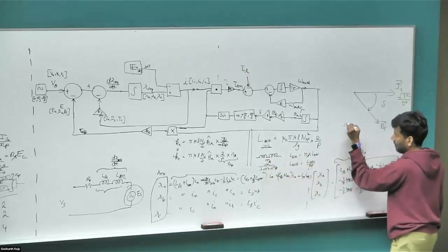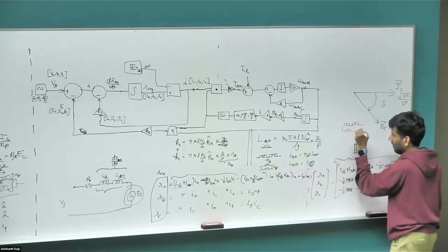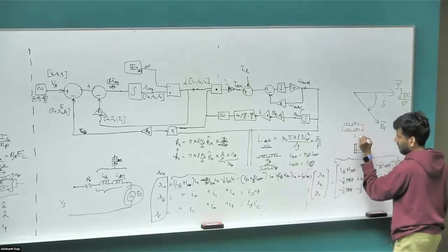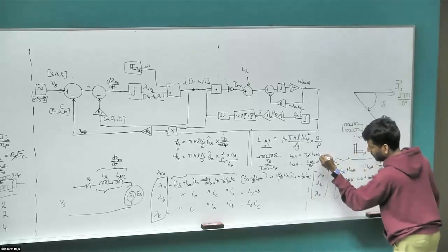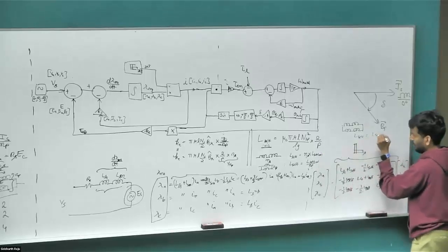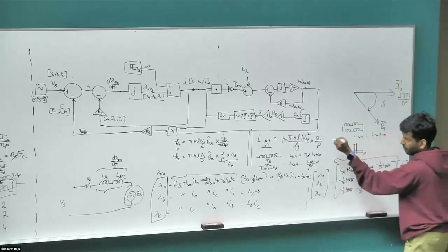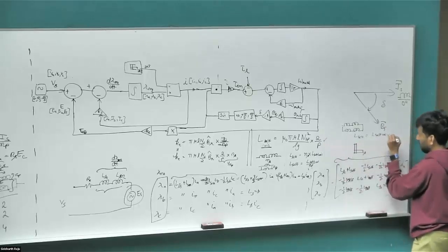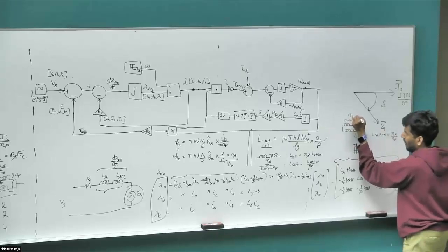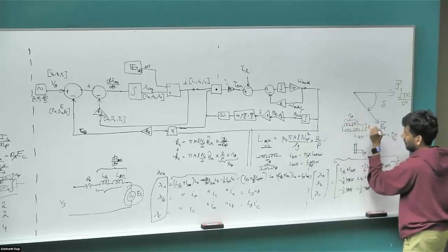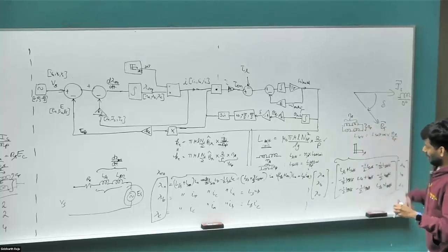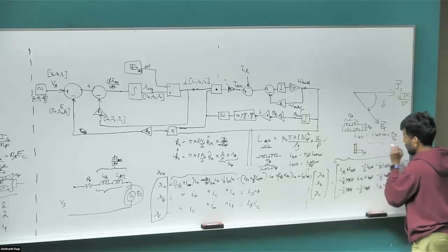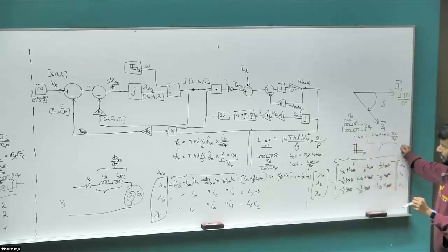Now, if you have a bunch of connections where there are a bunch of coils in series and another bunch of coils in parallel, then the net self-inductance is going to be equal to L self of coil, which is what our formula here is, times the number of series coils divided by the number of parallel pathways. Depending on how we connect this coil, this inductance term L self that I've used here is obtained in our model.